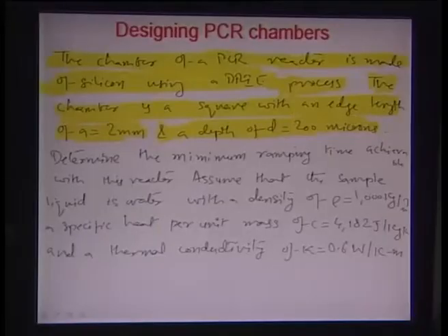Now, this is how micro architectures are normally designed. Another reason for this almost 1000 times increase in the linear xy dimensions of the chamber is that the idea is to spread a volume of fluid over a thin surface area. So, essentially you are taking a bulk volume of the fluid and spreading it over a thin film, so you can increase the heat transfer.